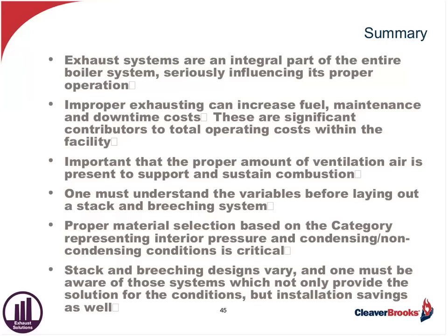You can put either a mechanical open-close and then be able to adjust, or you can put an automatic draft damper in to control it a little more precisely, especially if you have more than one boiler involved. We do that quite often. Each application has to be looked at individually.